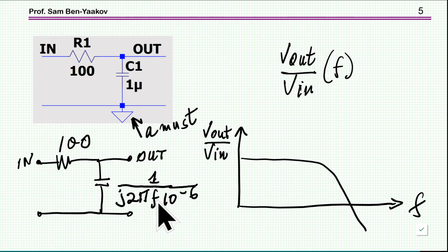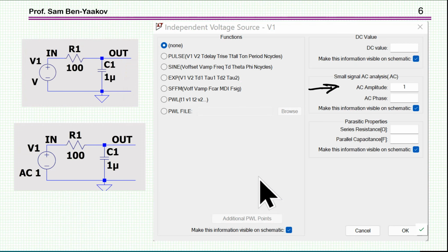Then for the range and the number of points that I've specified, it will calculate the transfer function in a phasor way between input and output, and then plot these, if I want the ratio or just the output, as a function of the frequency. So this is very basic AC analysis.